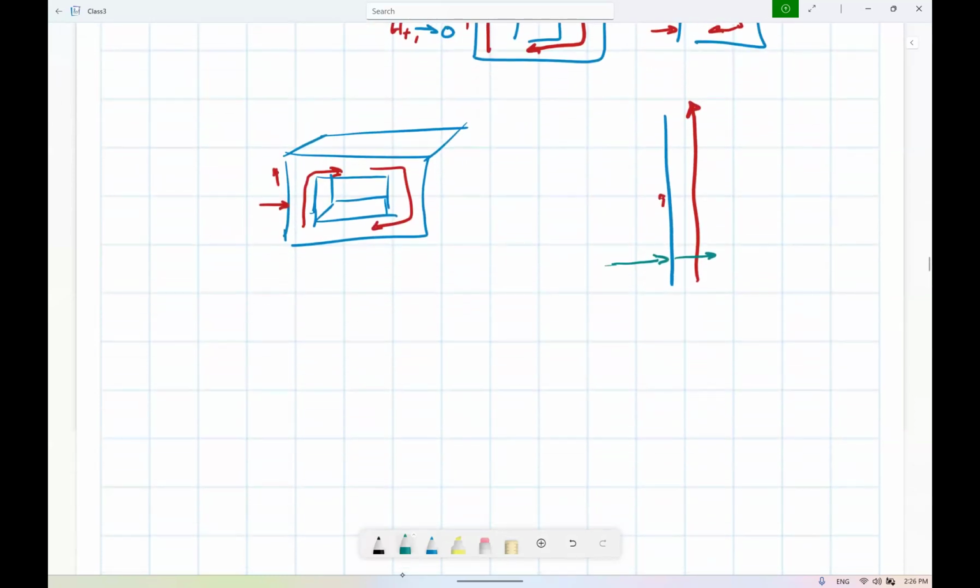This is another thing. Every time that you're doing a simulation that has magnetic material and non-magnetic material, the field entering the magnetic material is always at 90 degrees. If you see the field that is not at 90 degrees, you can immediately say, this is fishy, it's not good. You set up something incorrectly, most probably your boundary conditions. There are too many little details in the setting up of cases in finite elements that it's very easy to make a mistake. So to catch the situations when you make a mistake, you need to know these things.